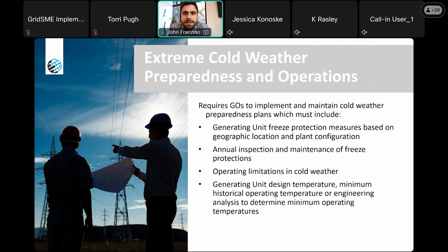They did not engineer those facilities for the type of cold weather that we actually had in the region. It was not part of the engineering design criteria, and thus we had critical failures. So that's where a cold weather preparedness plan steps in, to manage the 1 in 100 year cold weather event and make sure that we do not suffer reliability issues when that weather occurs.